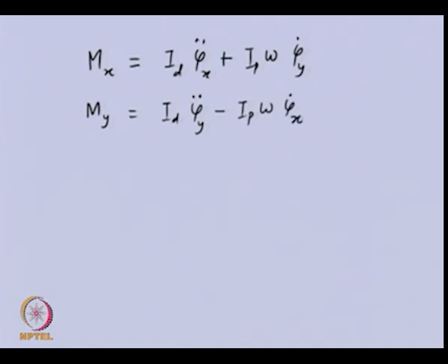So, basically if you see, this equation is similar to Newton's law, in which we equate the sum of all the external forces acting on the disc to the inertia term, because both are inertia terms. One comes from the diametral mass moment of inertia of the disc, another from the polar mass moment of inertia of the disc, and while obtaining the equation of motion we need to consider these two inertia terms.